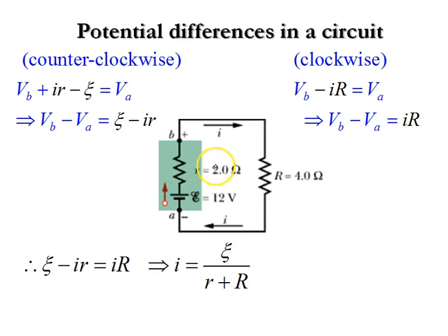And we also can think of this, well, we have a series loop. The sum of our resistances is R plus little r plus R. So we have, by Ohm's law, the total voltage across the loop divided by the total resistance in the loop gives us our current. So we have a third way to solve for this, and that's KVL, looking at potential differences throughout the circuit.